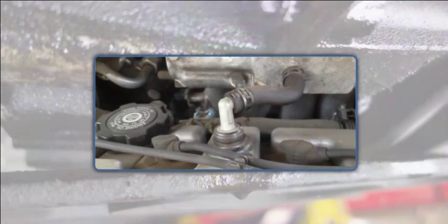Engine oil leaks can be caused by excessive crankcase pressures due to a faulty positive crankcase ventilation valve. This can force oil past seals and gaskets that are actually okay, but cannot handle the excessive pressure. Be sure to inspect the PCV valve and related hoses to verify proper operation. Some PCV systems require periodic service or valve replacement. Refer to the maintenance information for the vehicle you are working on.